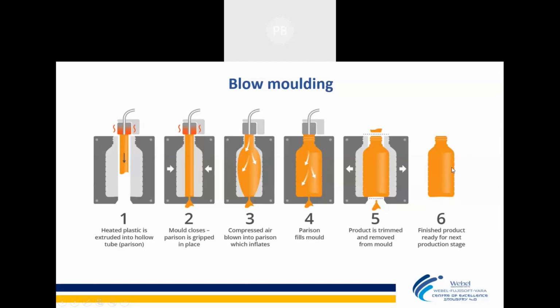Wherever there is development of bottles, wherever there is development of cans and all, blow molding takes place. So in that case, you can directly develop the dies with a 3D printer. If the die is a smaller shape, you can directly develop it with the 3D printer. For example, a 10 rupees water bottle or 20 rupees water bottle that we consume. Those dies can be directly made by a 3D printer and used, because here the temperature is not that high as compared to injection molding.